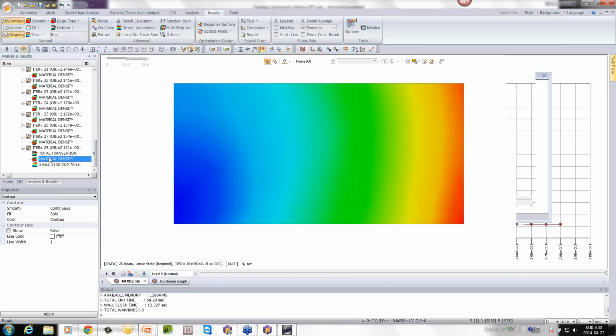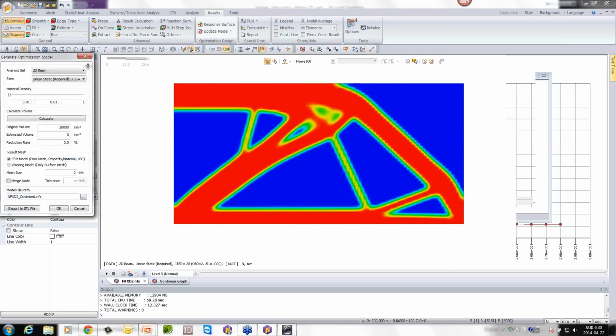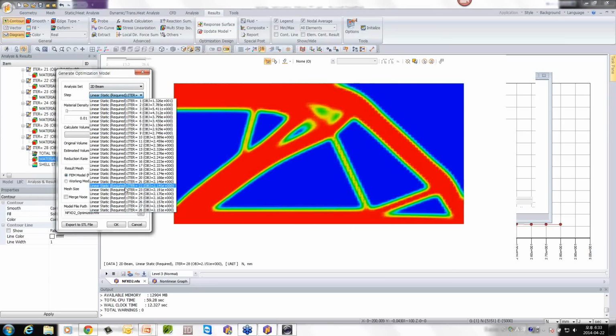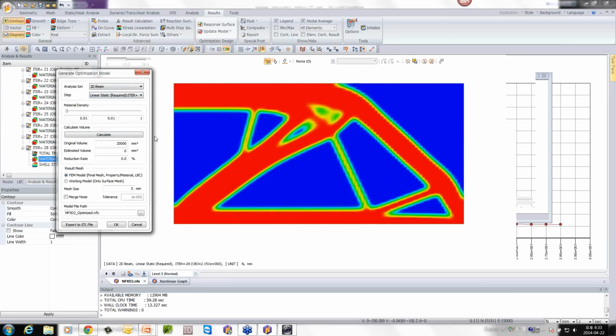And at the end you can verify the linear static analysis to view the result on the final shape. So when you got this result, you can update your model. So click on Topology Optimization. You can choose the step that you want to optimize. So it can be this one, for example, or the last one. At the same time, you remember that I checked medium for the checkerboard. So this is why you have still some part like that in gray, let's say, between the parts.